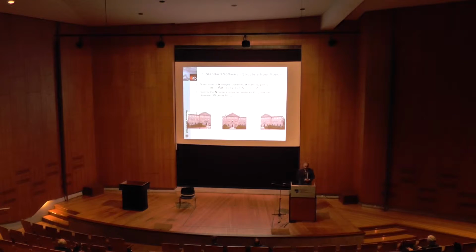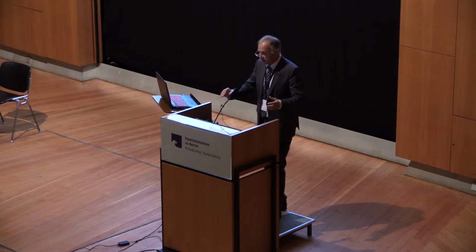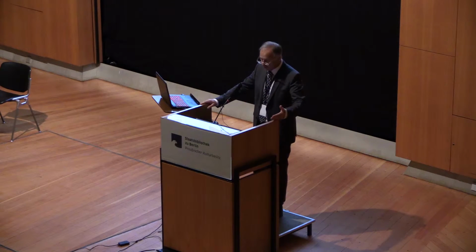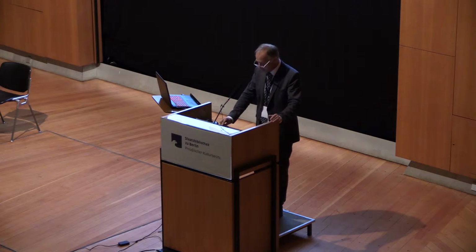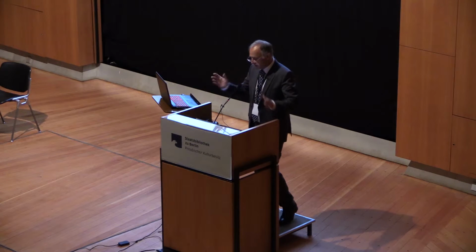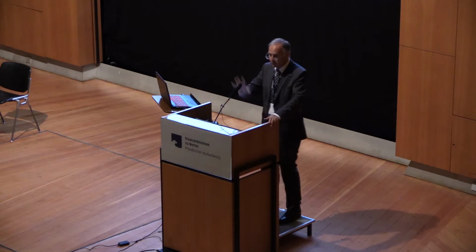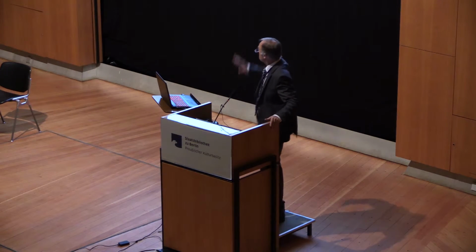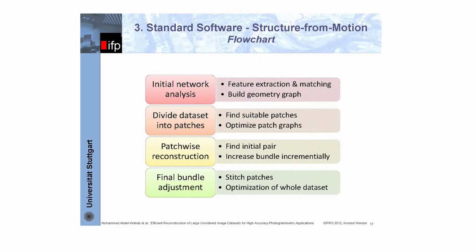So you see here, recover the N camera projection matrices, P, which are the orientation matrices, with observed 3D points in object space and finally mapped in the image. So we have developed our own structure from motion workflow in Stuttgart. We do a lot of graph theory, but here is just an overview. There is a lot of math behind it to solve everything automatically.